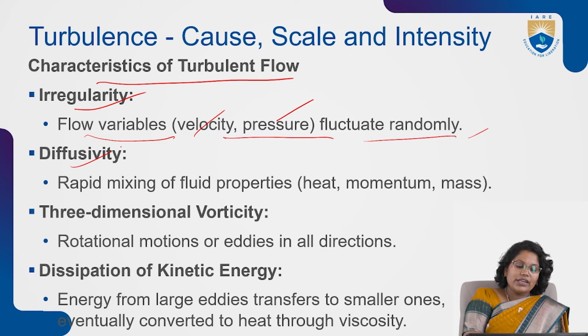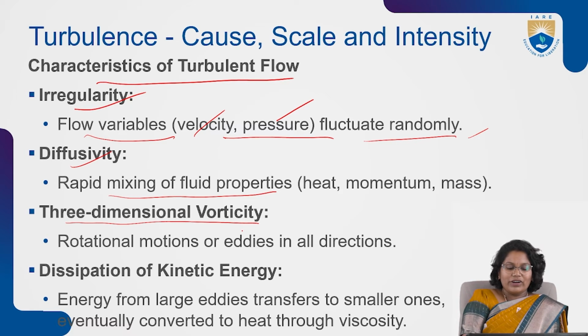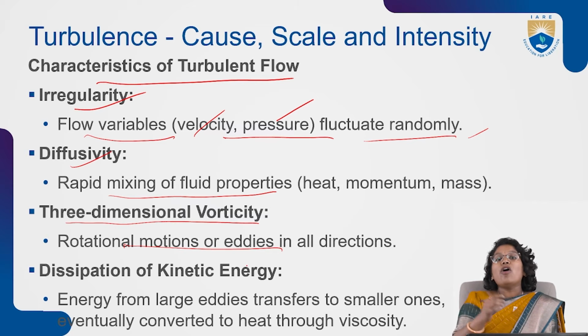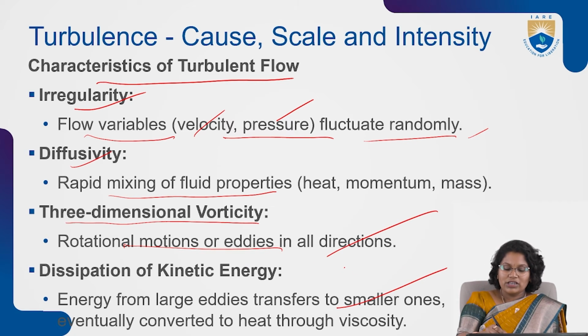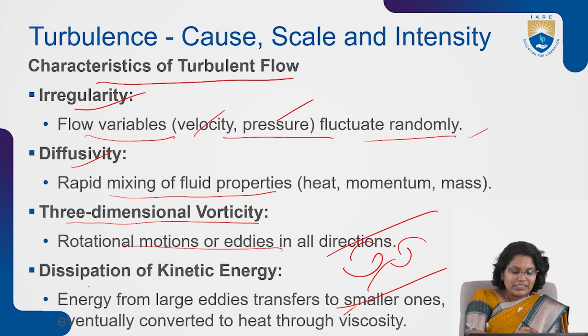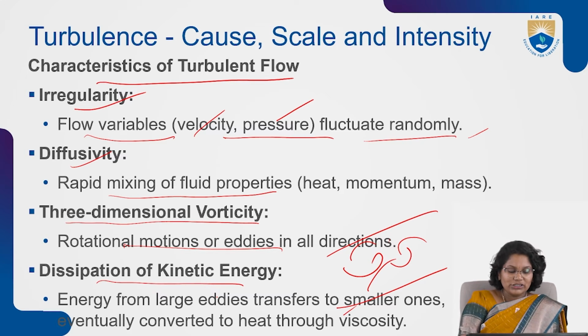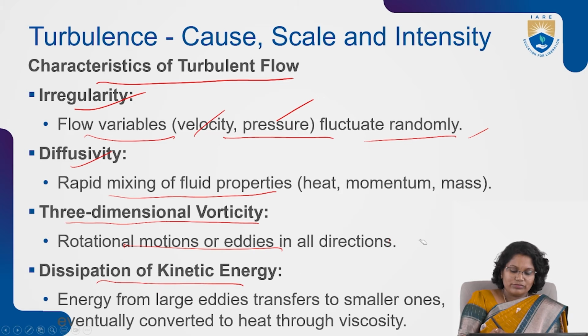Diffusivity is rapid mixing of fluid properties, such as heat and momentum, with rapid change in fluid properties. Three-dimensional vorticity: rotational motion and eddies in all directions. We see vorticity or rotation in all directions, unlike 2D. Dissipation of kinetic energy: energy from the larger eddies is transferred to smaller ones and eventually converted to heat through viscosity.